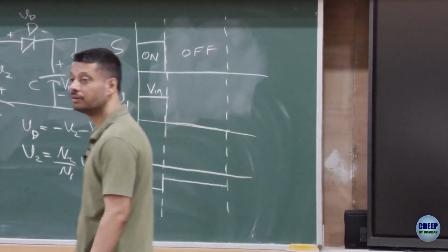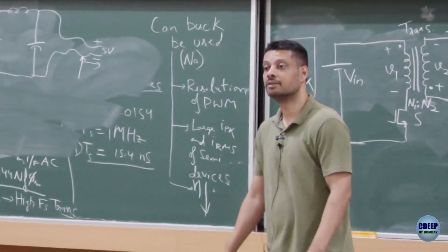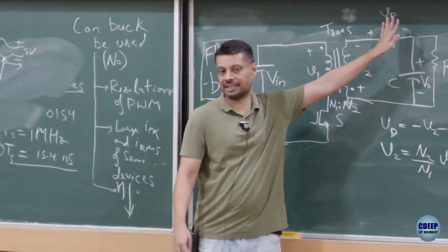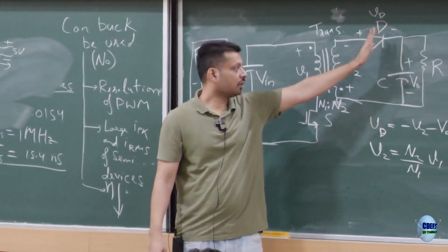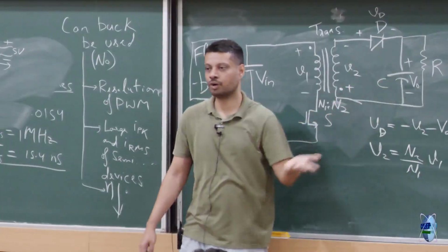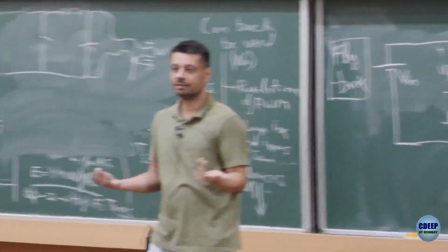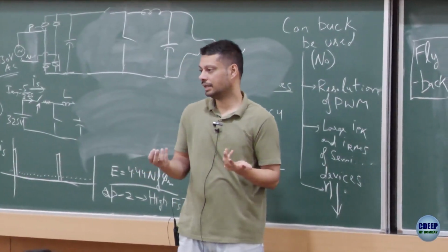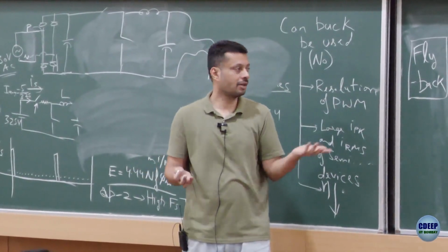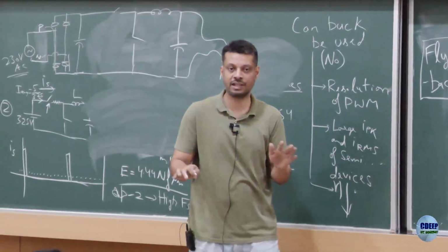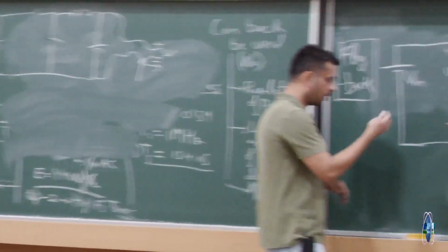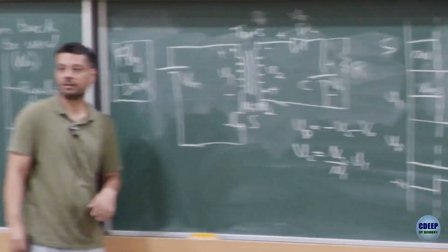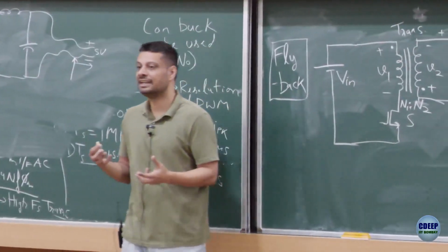But any other question or any other thoughts on this circuit? Why? Why do you have the diode, right? Yeah. So this is always off, so this is as good as not there. So how is the power getting transformed from input to output? It's not. So this is not a converter, it will not even work. If you put this, nothing will happen. Your output voltage will not get created, absolutely nothing. And for it to work, you need some form of inductor.